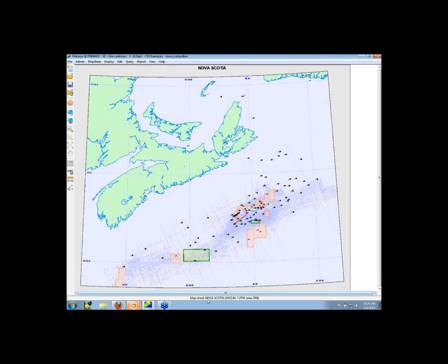And if you look towards the bottom of the map, I can see the name of my map sheet, but I can also see the projection system that is being used. So I'm using the WGS84 Geographic CRS with the UTM Zone 20 North projected CRS. And so that's a predefined projection system.